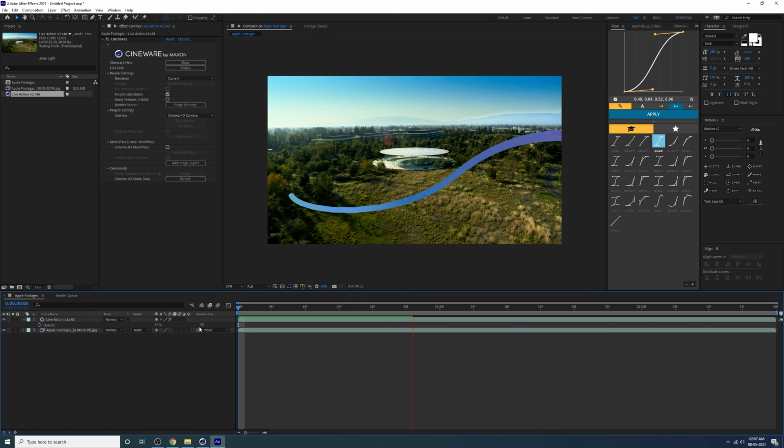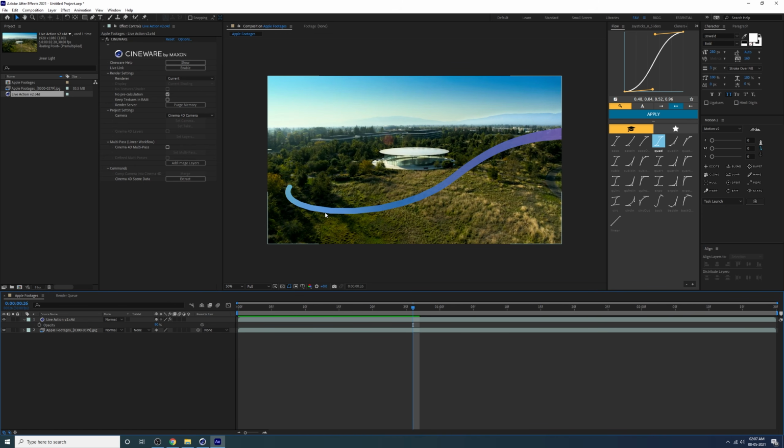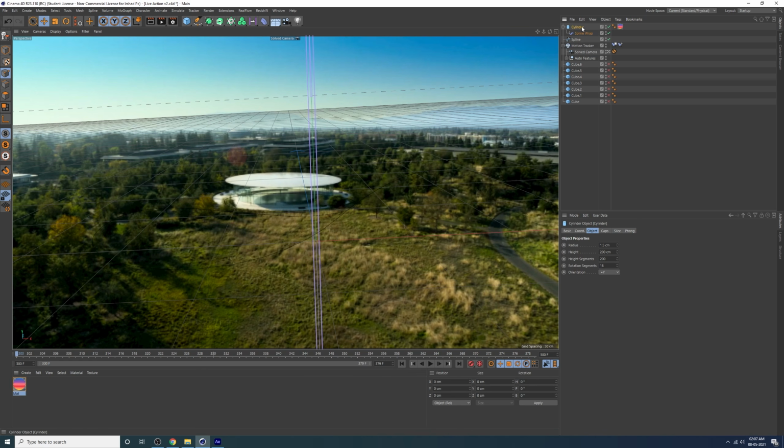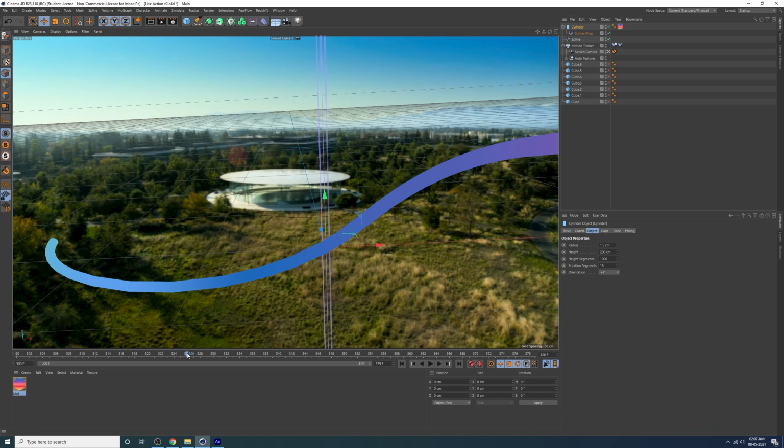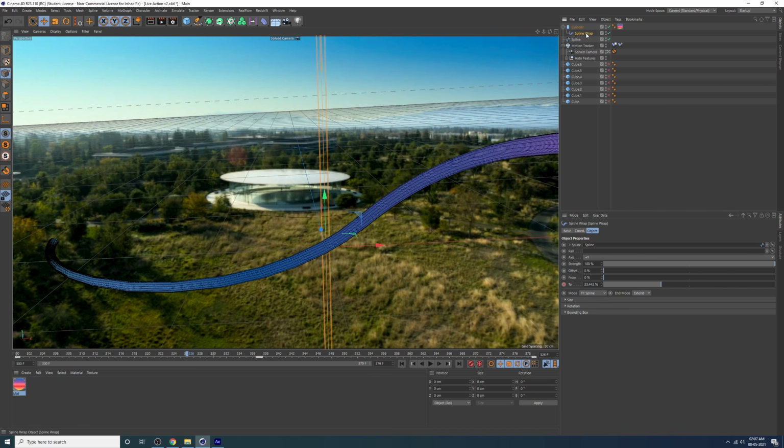See, I think this is again the problem here. You have to add more subdivisions. See, go to cylinder and height segments, maybe. And you can also add rotational segments. And also one more thing, remember that spline warp, and here instead of fit mode, change to keep length.